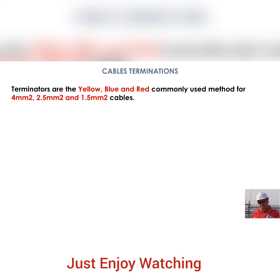So terminations with the yellow, blue, red are the commonly used method for 4 mm squared, 2.5 mm squared, and 1.5 mm squared size cables, guys. So when you see the cables terminated in our control panels, marshalling cabinets, fire and gas, and either in our switchgear, you can see the small size of cables, which are the lugs, yellow, blue, red. Easily you can identify what size of the cables they are utilizing in this termination.